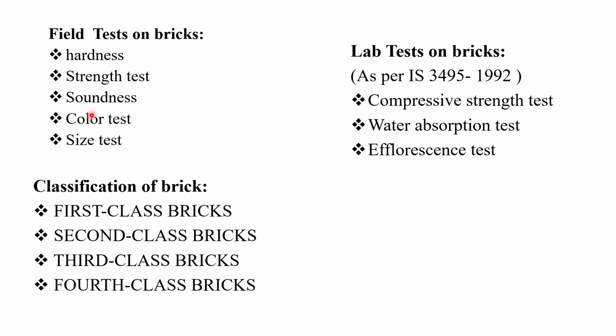So if a dull sound is there, that time we can say it is a weak brick, or the brick might break down. So a clear ringing or metallic sound should be audible.